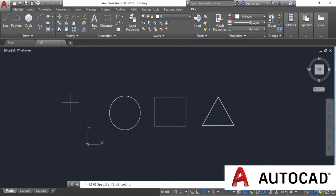So simply go to that command and left click and the command will now be activated. And once the command is active, you'll notice that its name and also the instruction will be visible on the command line, and also the cursor will change into this point selection cursor or into a pick box. In order to exit this, simply press the escape key. You can press escape multiple times also if you want, so that will not make any change to the drawing.